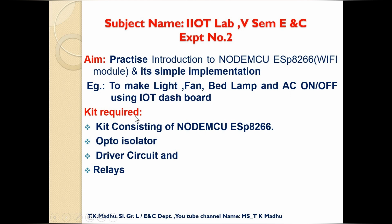So kit requirement. We need a NodeMCU ESP8266 and we have to use opto isolator, driver circuit and relays. So here it's a very important note that without opto isolator, better don't connect your laptop or desktop. Sometimes it may harm your laptop or desktop. I'll explain how it harms in a later slide.